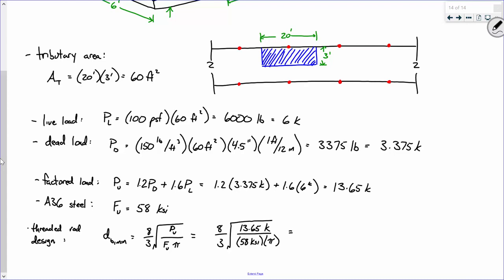0.73. Do I have a second on that? Take your time. All right, so we got a second on that. So 0.73 what? Inches. 0.73 inches. So if you were the designer and you were the one specking out this rod, what would you tell me to buy? Probably about 3/4. Exactly. 3/4 of an inch.